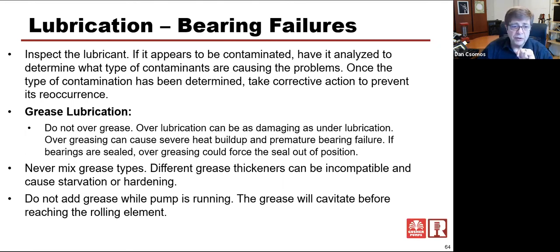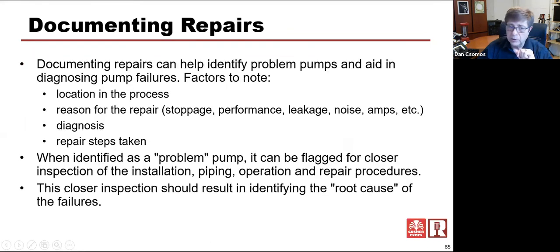Okay, we're just about finished at this point. One thing I wanted to talk to you a little bit about is if you have a customer that has pump problems, I would strongly suggest that they get into a routine of documenting the repairs. Seeing broken pieces and parts and seals that have failed really helps you diagnose what's going on in the system, and why pump problems are recurring.